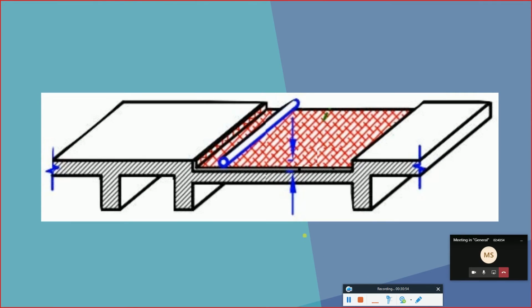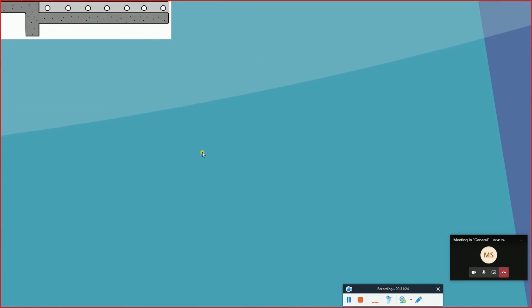Okay, and this is an illustration. So this is the regular slab, this is the sunken slab where we are having the pipes. After that we are going to backfill. Why do we backfill? Because we need to protect the pipes, one. Second, we need to reach the same level. So backfilling till we reach the finishing level, and then put whatever tiles or granite or whatever finishing material that you are having.